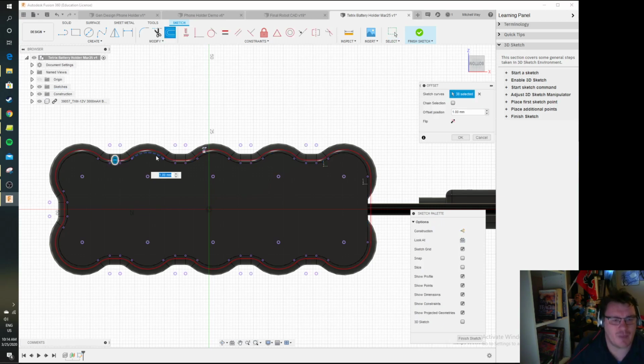Offset's one of your more powerful tools because if I go ahead and select an offset, here we go. Oh, it's already selected my curves. Fantastic. Since I'd already selected the thing, it's actually selected all of the things I need to offset. You can see that it's got 38 polylines selected right now. I could actually go in and unselect them if I wanted to. I don't right now. It's going to ask me how far do you want to offset.